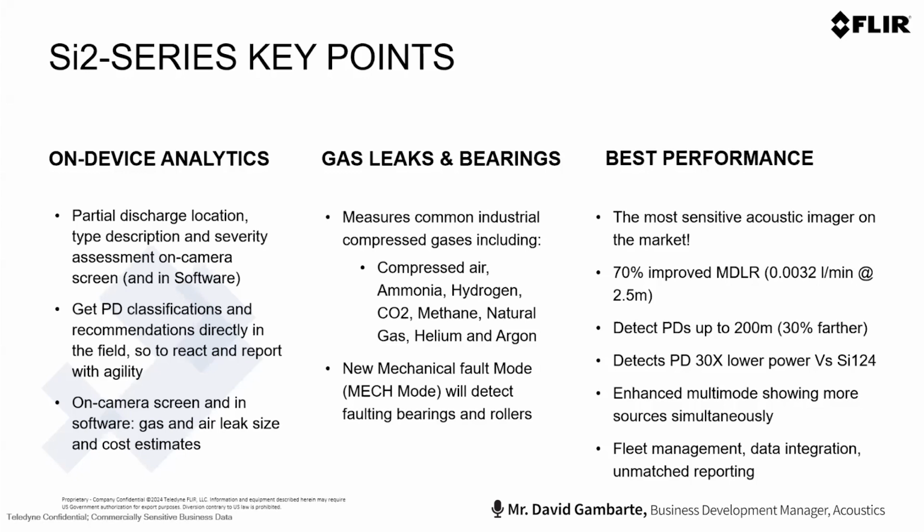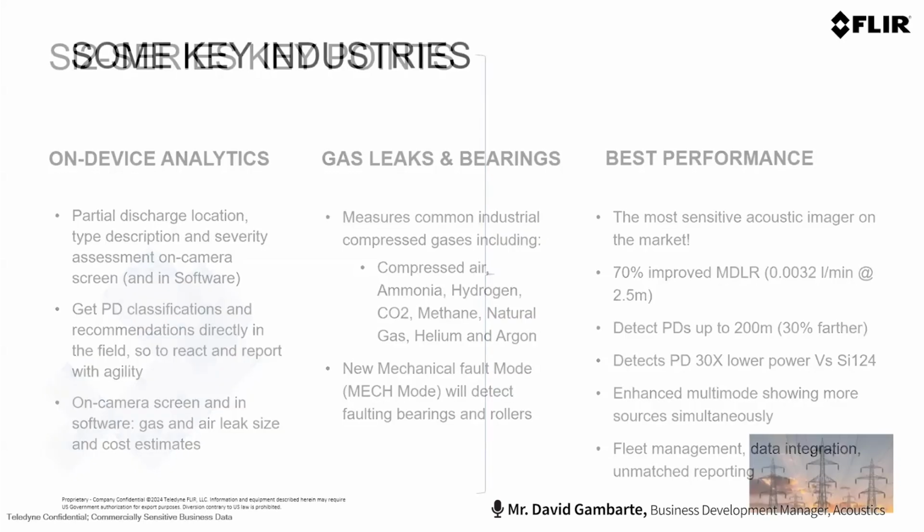With the multi-mode, when you get to a place, you want to go in multi-mode because you don't want to miss any phenomena, whether it's a partial discharge, a leak, or a mechanical fault. But then when you find that there are one, two, or three partial discharges, for example, you want to go to single mode and get the analytics of every one of them. So this is very important to be aware of. With multi-mode you will not miss a single one, because there could be a covering partial discharge or leak around. And then of course we have fleet management, data integration, and the reporting system.